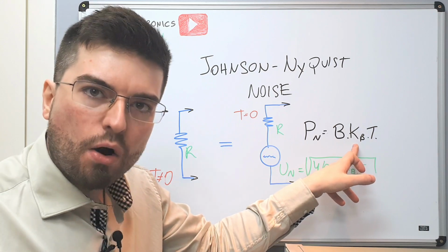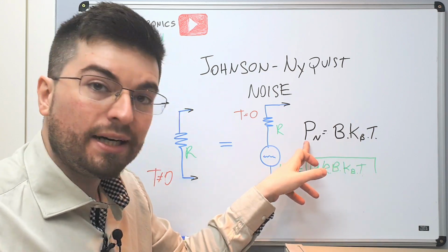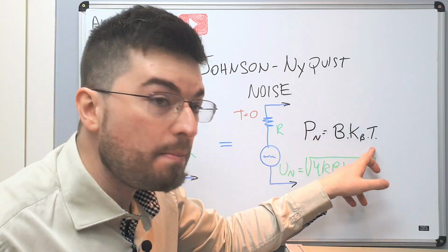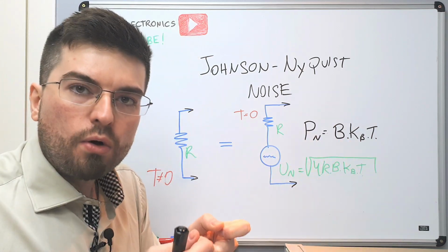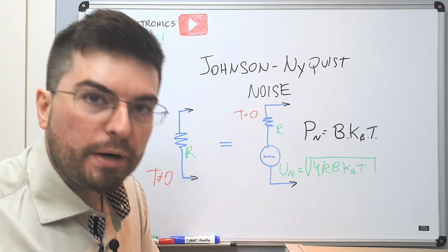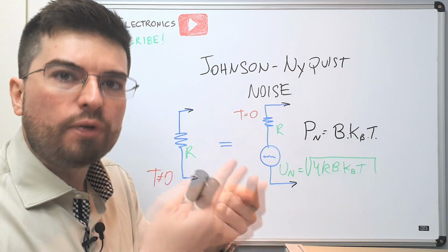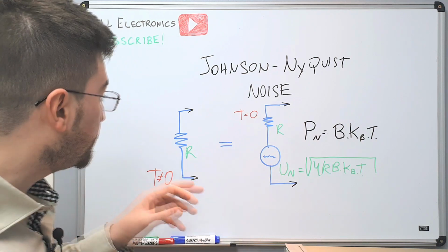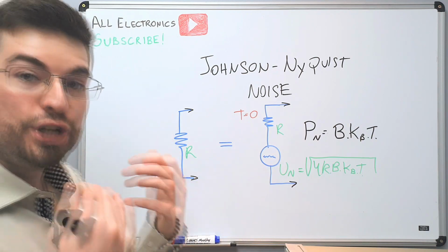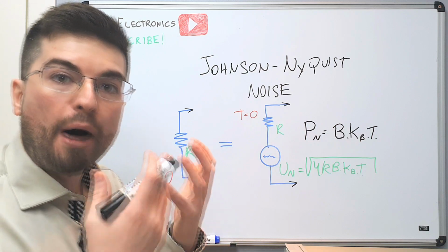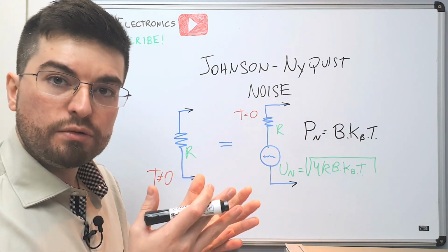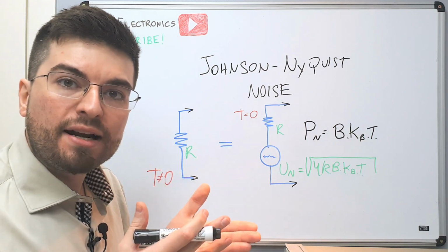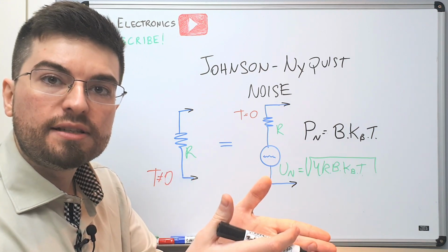Now we can talk about the noise power in terms of the temperature. So now we can talk about what temperature would generate that noise profile. What would be the temperature of this resistor here to generate an amount of power equivalent to the noise power that that amplifier is injecting into the system.